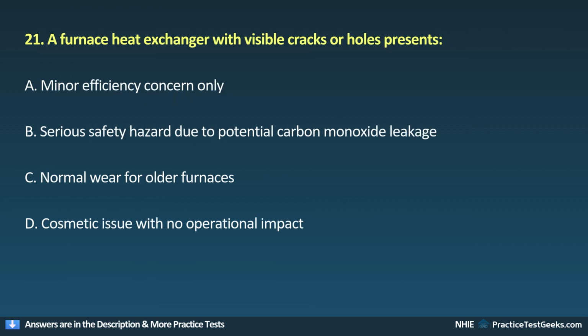21. A furnace heat exchanger with visible cracks or holes presents A. Minor efficiency concern only. B. Serious safety hazard due to potential carbon monoxide leakage. C. Normal wear for older furnaces. D. Cosmetic issue with no operational impact.